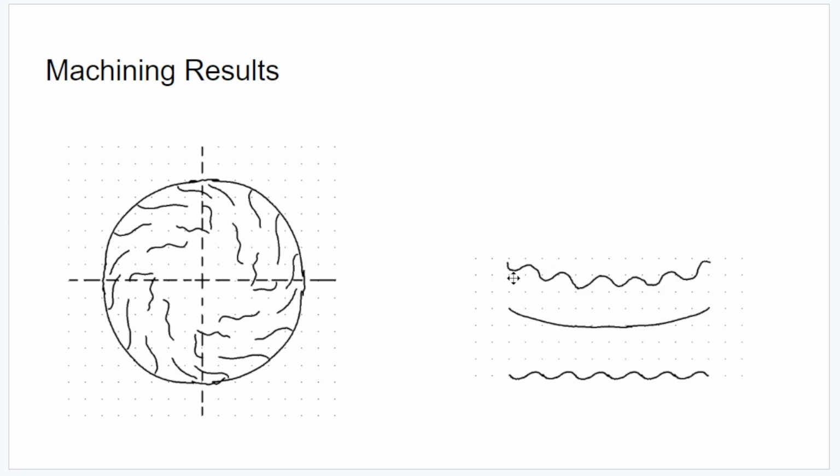Another side note, waviness. So this is sort of how you would split it up. If you had a surface that came out looking like this, you've got this periodic issue and then some overarching trend. So typically you would consider this to be the form error and then this to be the waviness error. Waviness and chatter typically come from some sort of harmonics in the machining process. So if you've got an unstable workpiece or it's poorly chucked up, you'll get a lot of waviness and chatter.